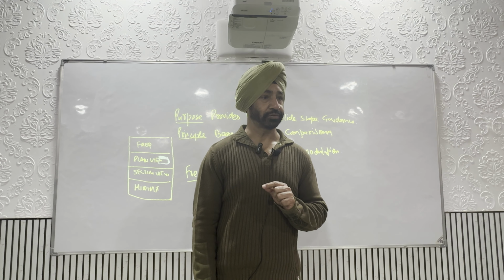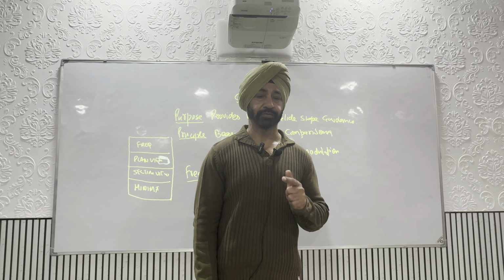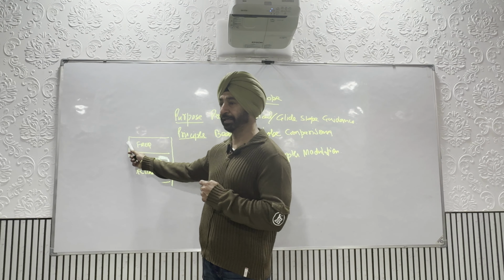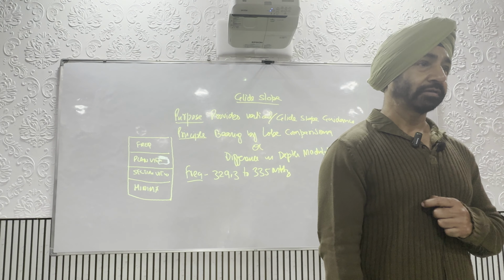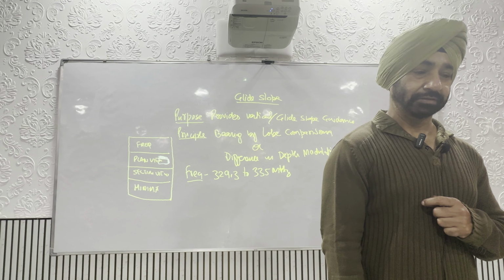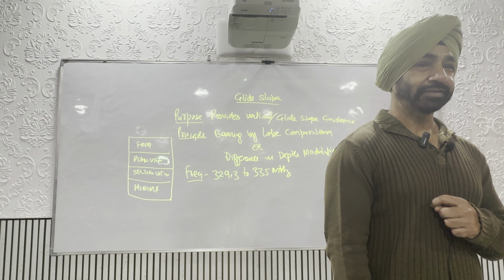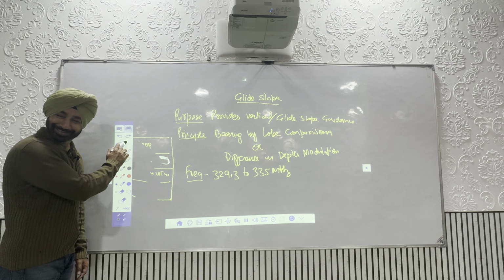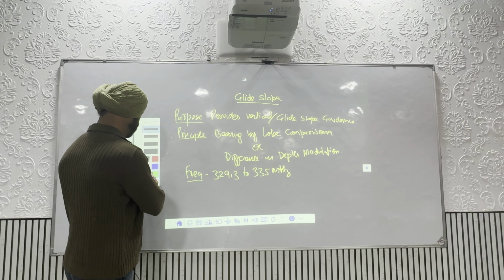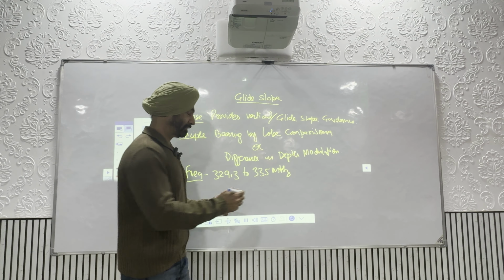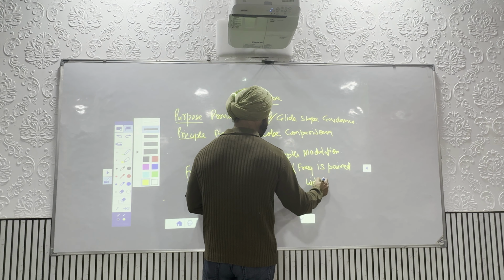You will find the frequency is also given there. ILS frequency 110.3. Similarly, where the frequencies are given on the top left, you can see that the localizer frequency 110.3 is given. Correct? You got it? Where is the glide slope frequency? It is not given. Then how do you tune it? It is not given in the chart primarily because it is paired with the ILS localizer.